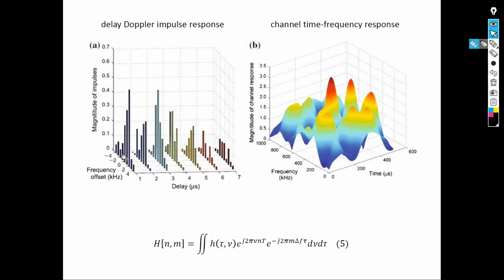And here the channel, you define it as 2D. It's like a matrix, not a vector, because you have values not only in one row or one column. You have multiple rows, multiple columns. This is how you define it in MATLAB. And you take FFT2 of this, and you can draw this. You can draw it with the plot3 function, plot3 or surf, okay? And this is the mathematical formula.